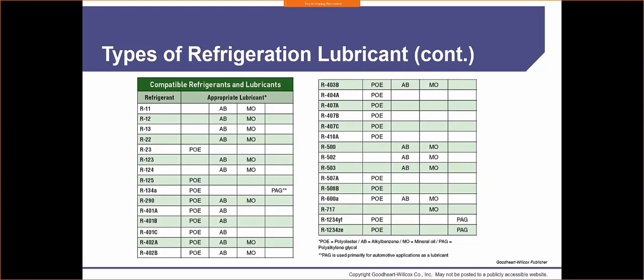So we've got compatible refrigerants and lubricants depending on the type of oil that we're working. Let's see, POE oil, 410A, if we go back to 22, MO, mineral oil. Like I said, a little bit of POE and MO is okay, but we're talking about whatever's left on the sidewalls of the system. We're not going to just pour jugs in and call it a day.